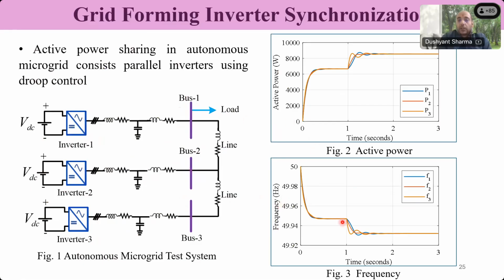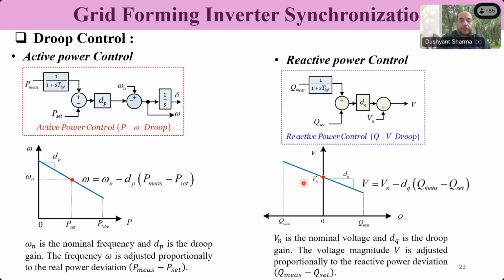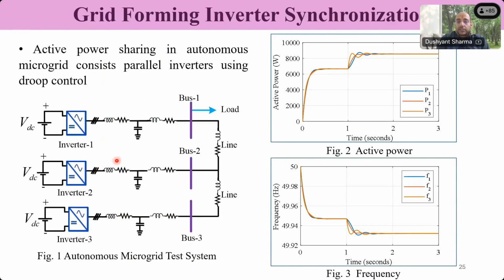As soon as the power changes, we change the frequency, so that, at a steady state we cannot have two frequencies. So automatically, if there is a frequency difference, there will be angle difference. If there is an angle difference, there will be a power flow. If there is a power flow, our controller that we have developed here, where we are intentionally changing the frequency, will retune itself so that at the end of the day, all the sources operate at a common point P at a common frequency F.